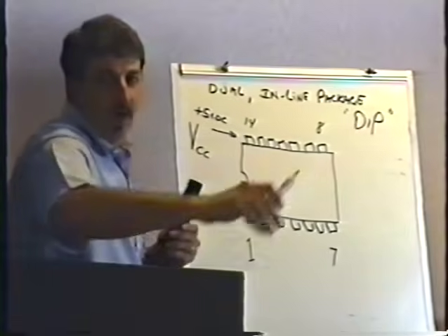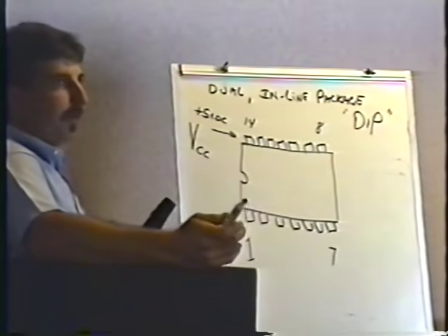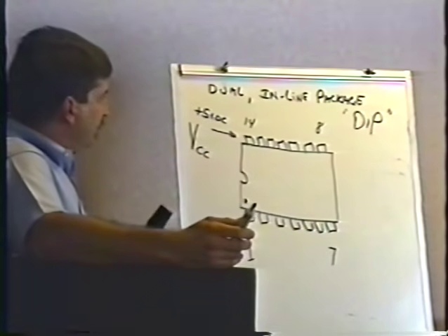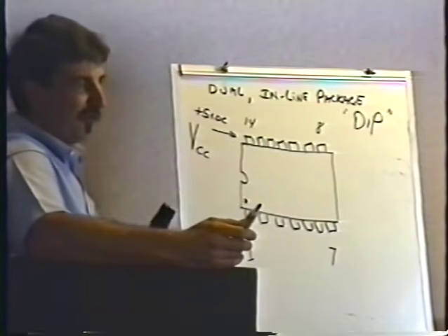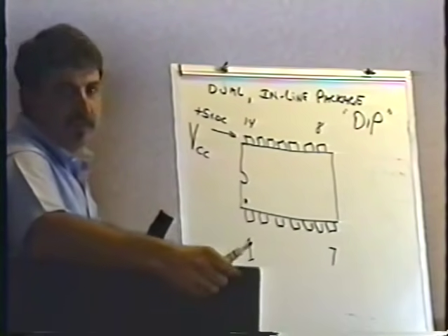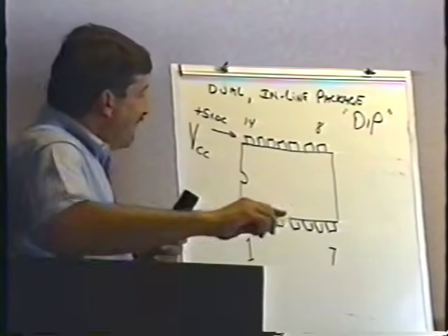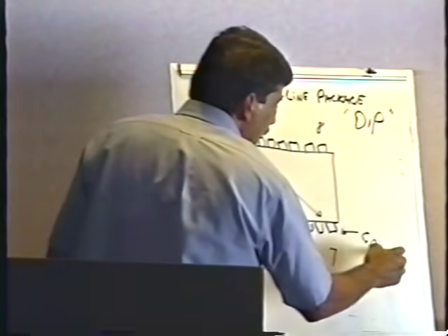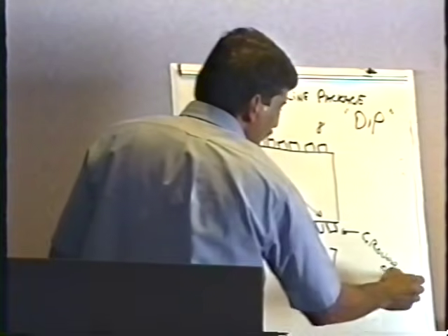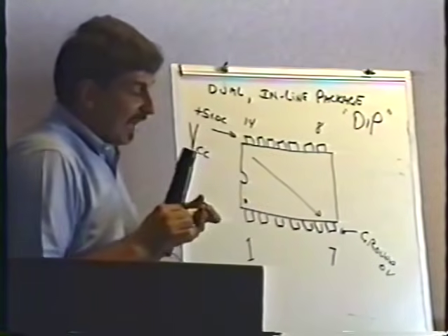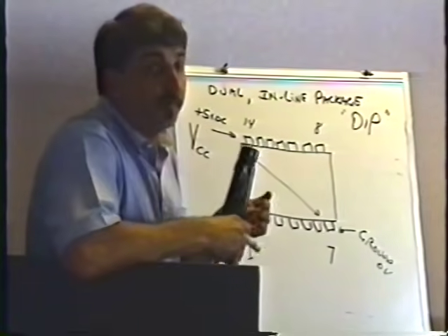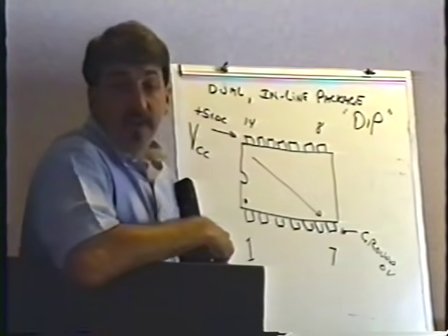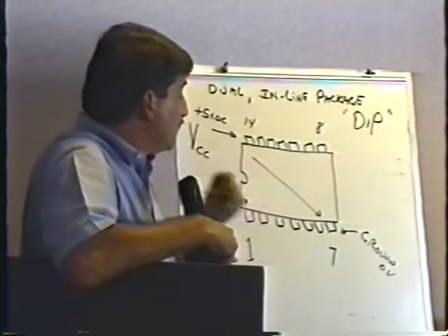I've no idea why it's called that, but in case somebody asks, did you check your VCC? Yeah, it means check the 5 volts. And then kitty corner across the chip on this other side right here, this is ground, which of course is 0 volts. When I want to check the 5-volt power supply on something, I don't usually go to the edge connector. What I usually do is go across a chip.